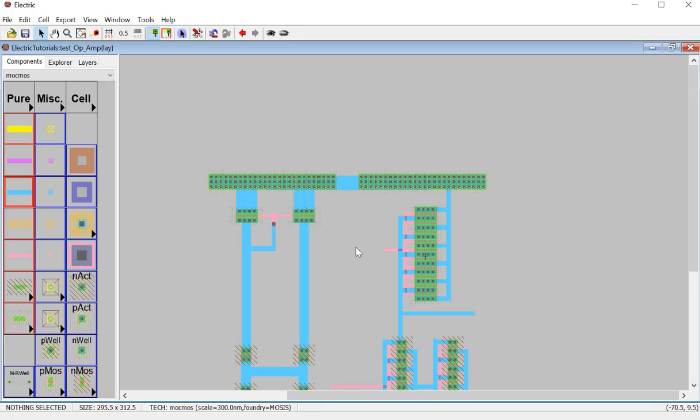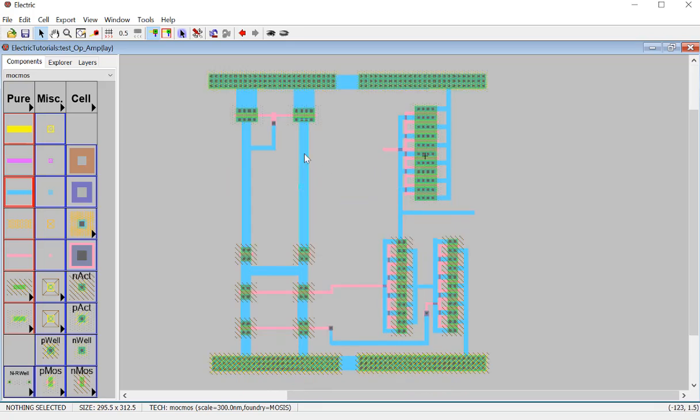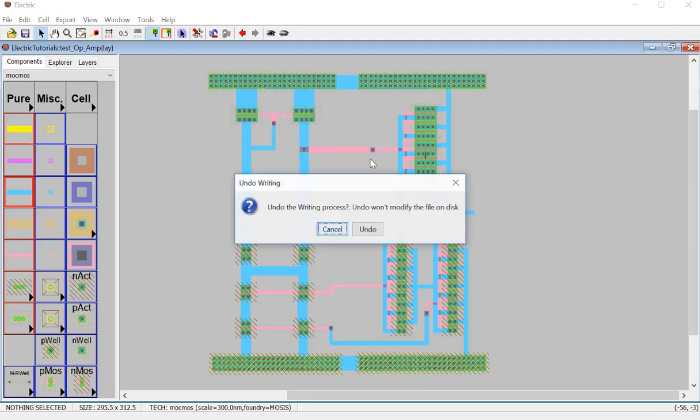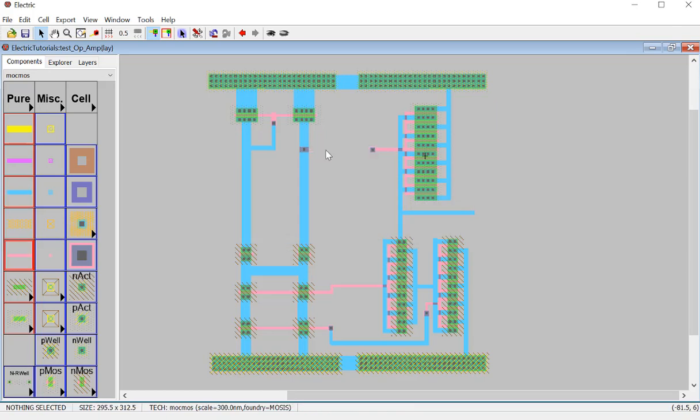All right, so that's the output, right? Output of the differential pair, and we want to connect it to the gain stage. So this is how that works. If you don't want to do this, I think no, that's not good. So let's delete that one, use the metal one to connect it. No, you want to pick up a node like this, a metal one.